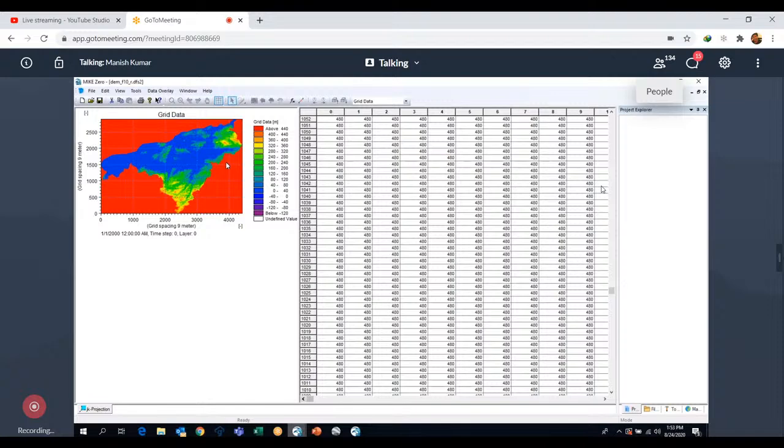So once you do that land boundary, now here it's important. Suppose some river is entering here. Suppose some reservoir is here at one boundary, and the release from that reservoir is entering into this 2D model. And if there are some excess releases from the reservoir, you want to see the flood inundation mapping. Then for these grid cells, I can give the actual elevation value. I can make it an open boundary condition.